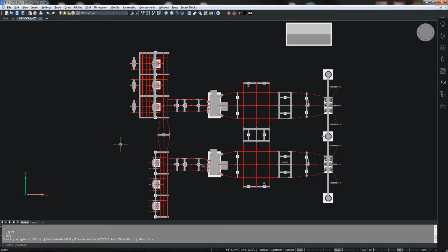One of the most popular applications for designing lightning protection systems and substations is the rolling sphere method based on IEEE Standard 998. However, this method is going to be daunting for many designers, causing them to revert to add-on or standalone apps that require additional investment. This video will cover the graphic design of substation lightning protection using the equations for the rolling sphere method, but applied utilizing your vanilla AutoCAD and standard AutoCAD commands and simple AutoLisp routines.